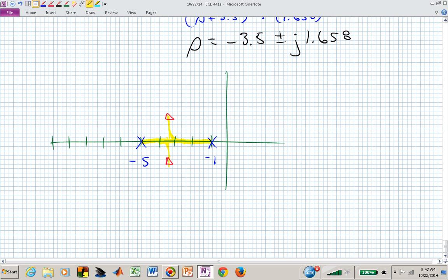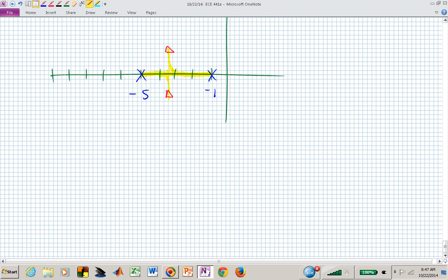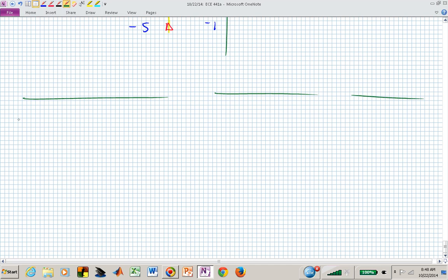Is that a little bit better than before as far as settling time? What's our dominant pole now? They're now at 3.5, aren't they? Our sigma is 3.5, which is better than 2.5. So it is better, isn't it? So now our settling time is getting smaller. Maybe it's not quite at the value of 4 that we want. Oh, but let's now just keep going. This was giving us something pretty close. What if we now just double it again and say K is equal to 2?